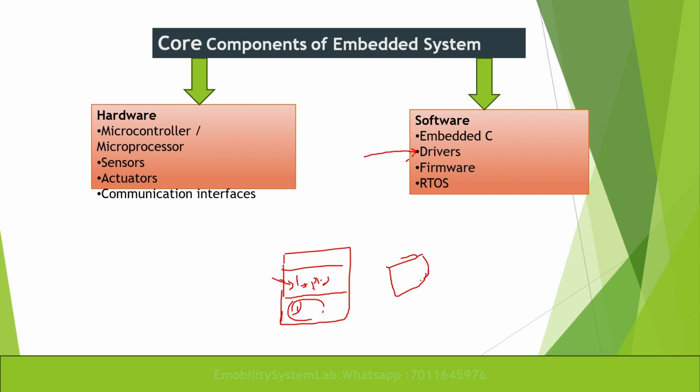When you work on CAN, then you have to initialize the CAN protocol and configure the pins related to the CAN protocol. Then you generate the code, and STM32CubeIDE will give you the drivers related to the CAN protocol. So what is firmware? Basically, that software is called firmware.